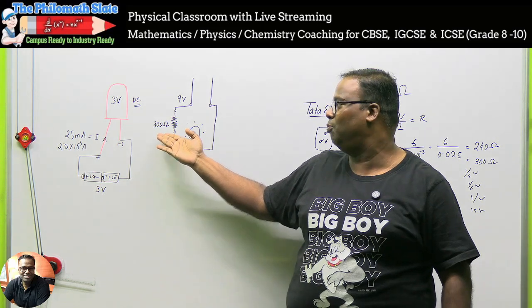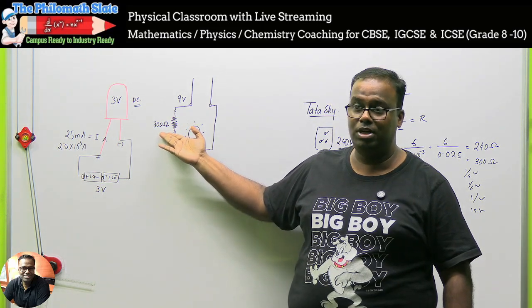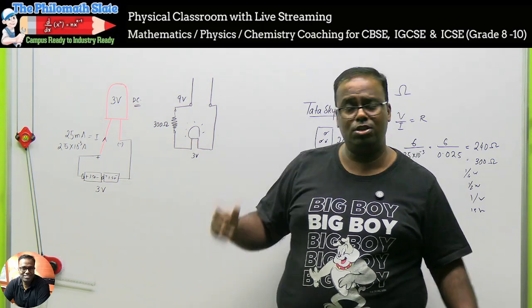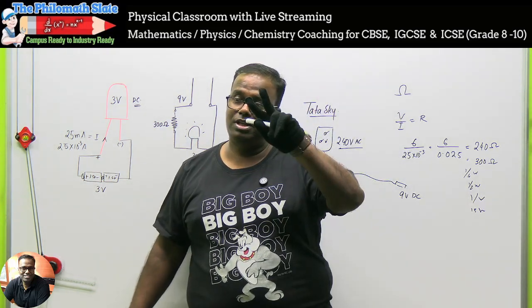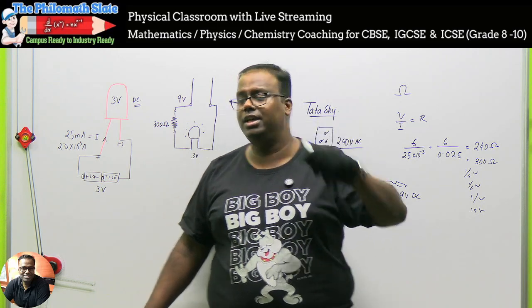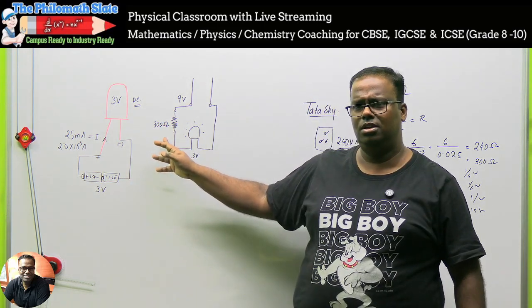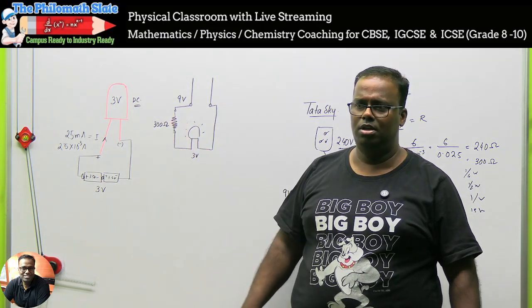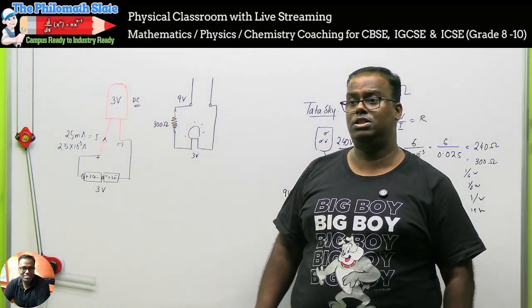So if P is the power of this particular resistor, the heat that is coming up or the power that is consumed, we'll buy a resistor of 300 ohms of 2P. We'll double it. In that case, it's comfortable. So you switch it on in the morning, and even when you come back in the evening and touch it, nothing is hot, because it has the ability to dissipate that much heat.